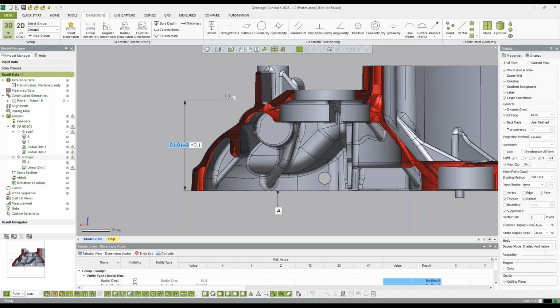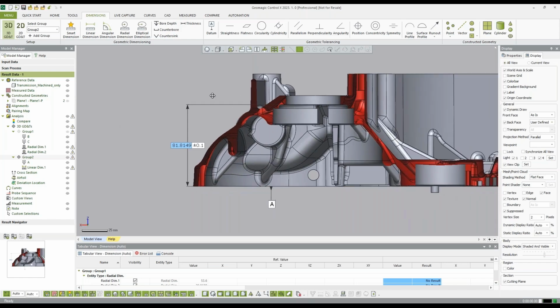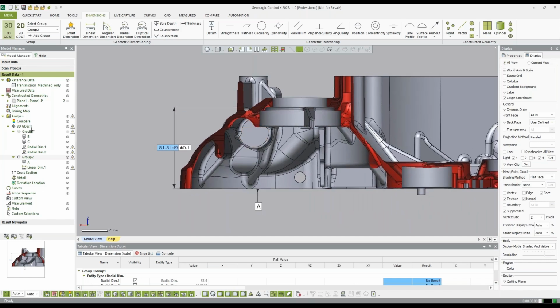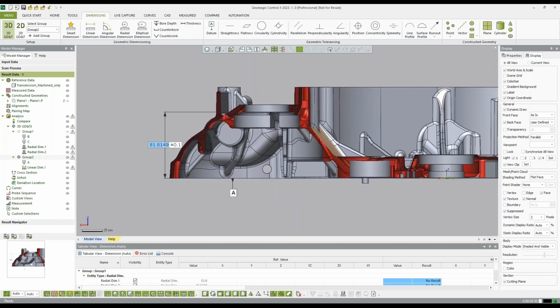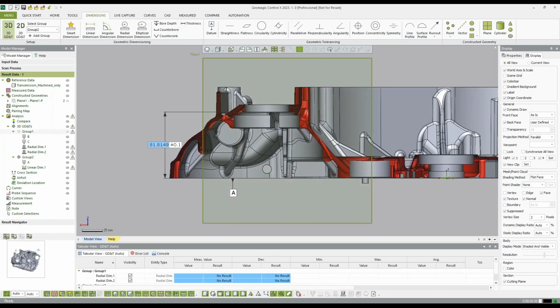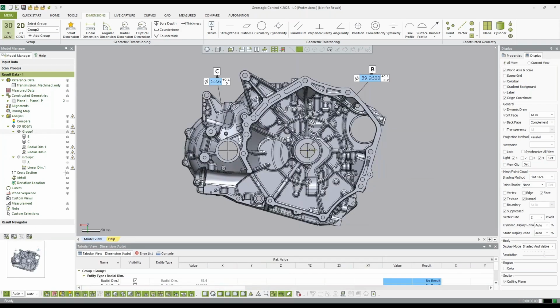So I always think about it and run through how we want to look at things. So again, this is all pre-planned, and these are saved view states. So if I added that into group 1, or if I wanted to add some other dimensions in here, I can do that. And then as I move around, I will just come back here and hit reapply, and you'll see it automatically turns off everything else, okay? And saves that view state.